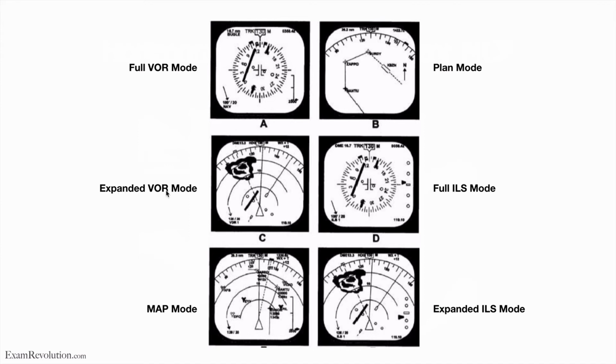So it's VOR mode because it doesn't have a glide slope. And it's full VOR mode because you can see the full VOR. Then you've got expanded VOR mode. Okay, now what is the difference? Well, it still shows you the VOR and the triangle as the aircraft. You can see there's the line of the VOR, there's the dots, right? In this case, we've only got 2 dots on each side, right? And you guys know by now that 10 degrees is full deflection. So obviously each of these dots are 5 degrees, right? So this is the expanded VOR mode. So can you see that they literally just zoom into that part of the VOR, right? You can see there's the circle for that top part. And then your VOR is shown over here, and you can see some of your track, and that over there is typically weather, right? So you might have weather that is overlaid on your VOR. Okay, so this is called expanded VOR mode.